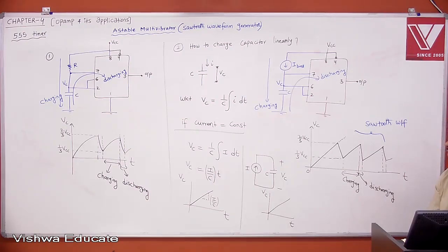And I'll explain the application of monostable multivibrator, which is nothing but pulse stretcher. Whatever triggers you are giving, that is nothing but input. Then we can stretch it. Whenever you get a control signal from a microcontroller, which is a very small trigger, and if you want to get some light out of it to represent the trigger, people use a pulse stretcher. Whatever trigger you are applying will be stretched if you apply it to a monostable multivibrator using 555 timer. Okay, that part I'll explain.